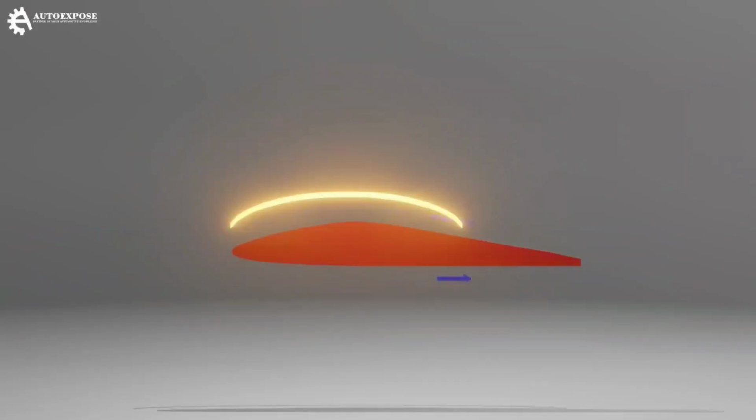But if the top is made slightly curved, it will extend the area in contact with the air. Because the air flowing on this object is constant, but the distance traveled on the upper side is further, the air will move faster when passing through the curved area. As a result, the pressure on the upper side becomes lower than the lower side. Well, this is what causes lift.